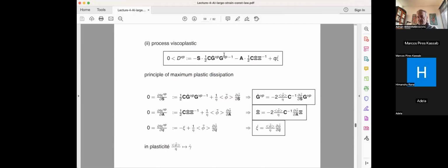So when I take the derivative from that type of penalty term, I get my Macaulay bracket, and so I can see if I have the derivatives of this regularized potential, which is viscoplastic deformation plus this penalty term. From the first term, I recover the evolution equation of the viscoplastic deformation to be expressed this way.